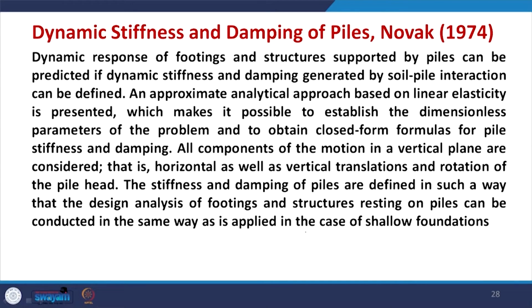So, whatever the solutions given by Novak, those solutions have been later on very much used, because they have given the stiffness, and once you have the dynamic stiffness, it can be used like a spring and dashpot. And this is one thing that needs to be understood, these dynamic stiffness and damping, when we say it is of piles, it is not only of the pile, actually this is for the soil pile system. So, the idea is that later on people have replaced the soil pile system with the spring and dashpot, and then the rest of the analysis they have done like a structural analysis. So, the task has been made very simple.